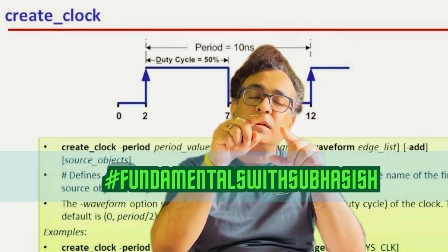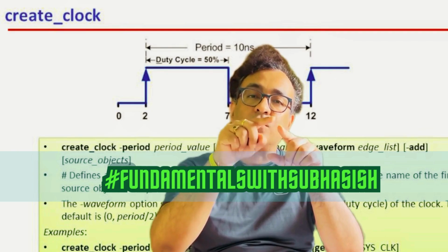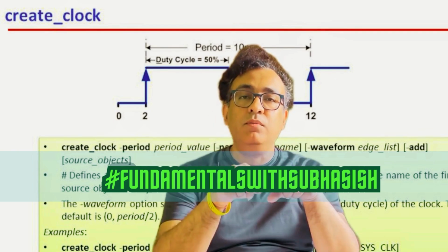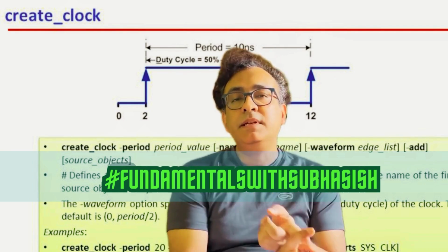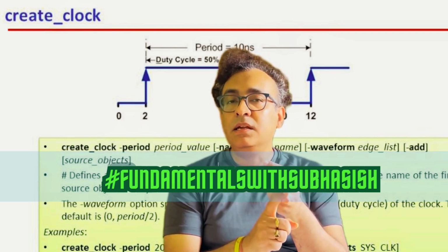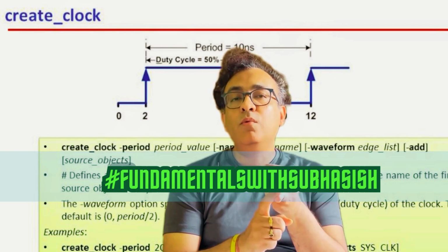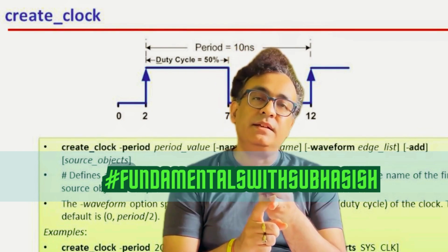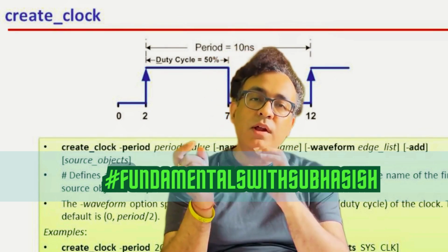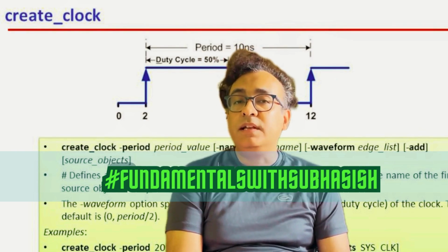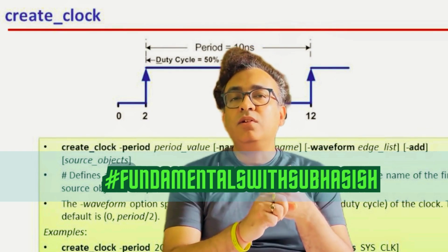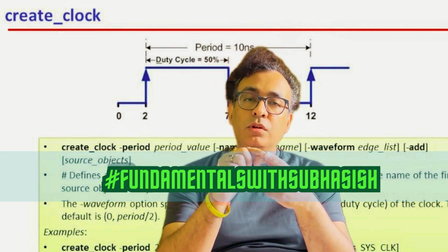This does not mean that you want the design to create a clock at that point; it is just for applying some constraint on the particular block itself. Create_clock has some parameters to provide: one is period, another is waveform, and another is the particular pin name where you want to provide the create_clock, et cetera. Today we'll talk more on the conceptual side of things. You can find the help page or man page for create_clock in the Synopsys design constraint documentation. So this create_clock is provided on the module boundary.